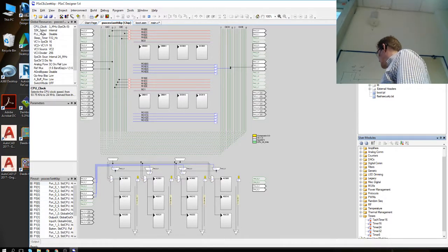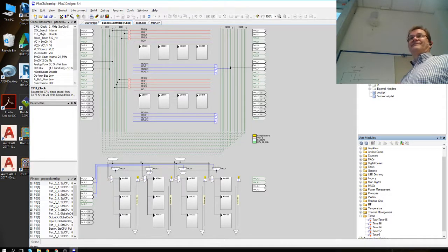We start from the 32K clock and divide it by 2 to the power of 14, which means a 16-bit counter, and this one would be giving the interrupts. Good. So we need a 16-bit timer.